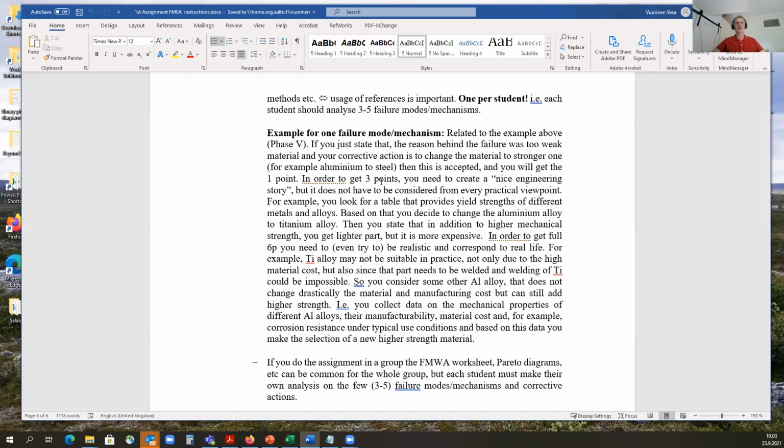You go to the literature, you search for aluminum alloys which have different alloying elements, like instead of the cheap aluminum zinc alloy, you go to some aluminum magnesium alloys, used in aeroplanes or whatever, and you can improve the mechanical properties without drastically increasing the cost.